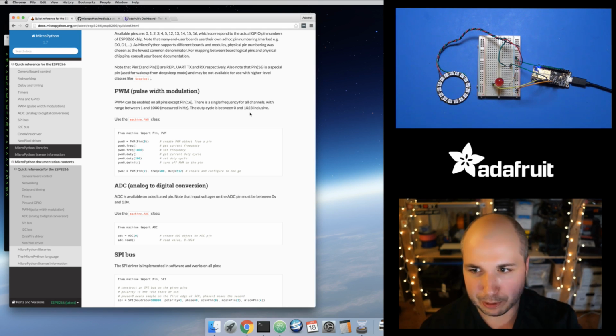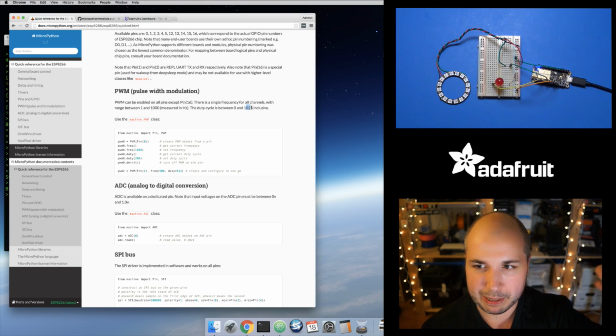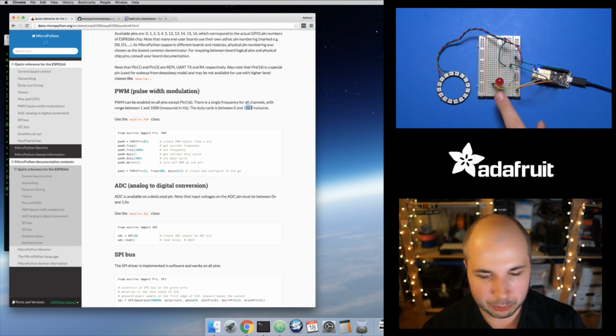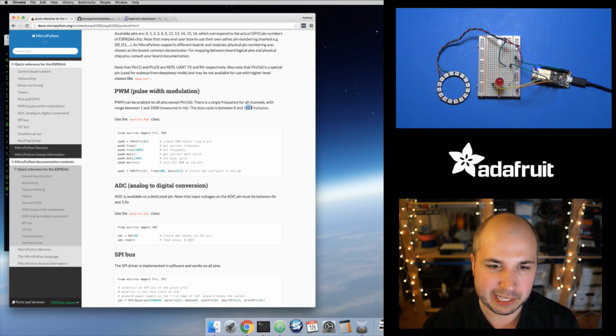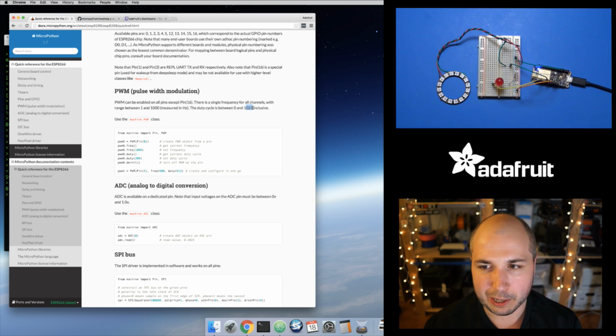It's never above the 0 voltage level. Versus if it's halfway in between 0 and 1023, so if it's like 512 or so, then it's at a high level for half the time and a low level for half the time, which would average out to look like half as bright. And if I set it to 1023, then that just means it's going to be on for the entire waveform. So it's going to be full brightness effectively.